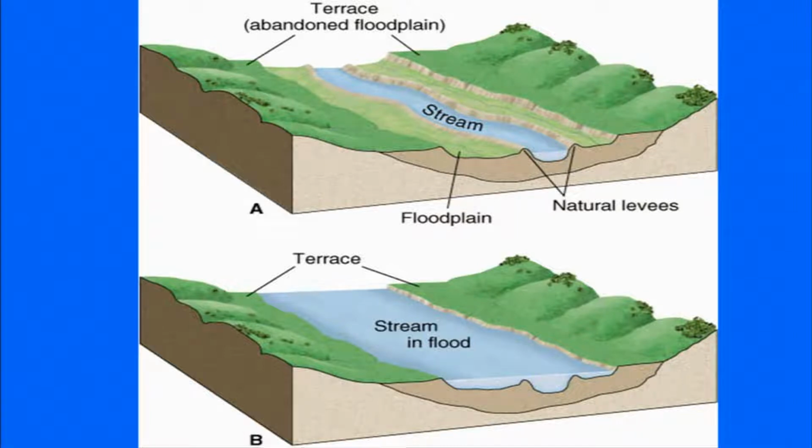So what we see in the upper figure A is some flat surfaces adjacent to the river valley, or you can say that this white area is the river valley, which includes the step-like landforms which have been seen here. So if you see in the profile, you see a step-like feature here. So this is a natural levee, but this is also a part of terraces. So terrace 1 and terrace 2, and similarly you see the terrace on the other side also.